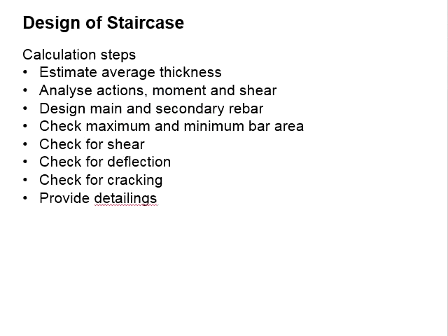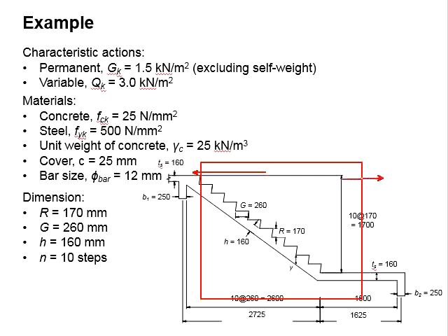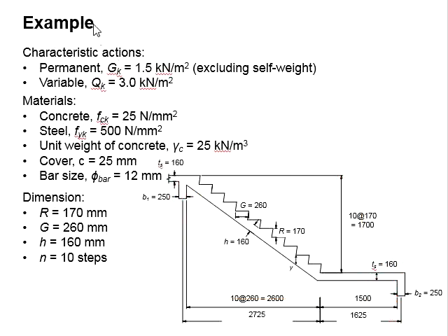Now that you have designed the main reinforcement bar on the basis of the ultimate limit state, the secondary reinforcement bar, you know, is not meant to resist the bending moment, as the staircase is designed to withstand the load in the one span direction. The bending moment will occur in this direction, but not in the transverse direction.